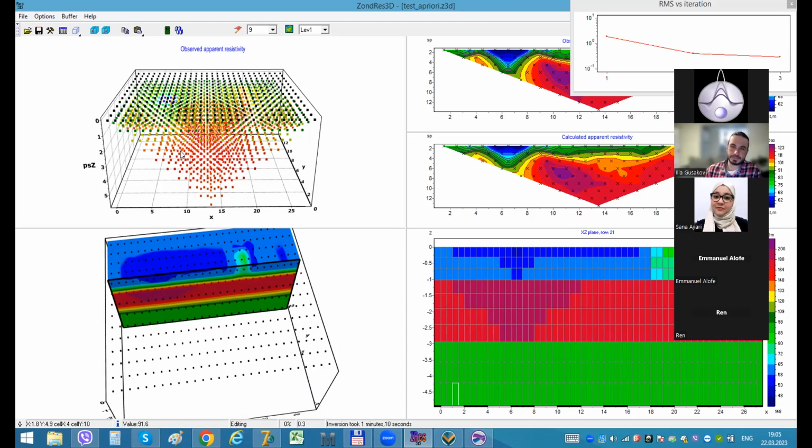This is very simple. If you need to set just a simple water layer, you can use the topography section of your data file, and instead of the topo word, you use the topo plus W word, and add 3 parameters: water resistivity, water level, which is usually 0, and number of subdivisions.